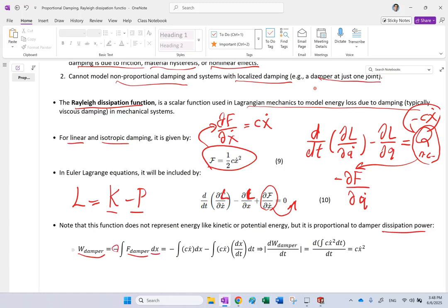That negative is because the damper is against the displacement, so there is a cosine of 180 degrees, the angle between them, because this is like F dot dr, and F of damper has this magnitude, dr has magnitude dx, and the angle between them is 180, so cosine of that is -1. Now F of damper is c x dot, linear isotropic damper, and then dx, you write it. Now here I divide this dx by dt, multiply by dt, so this term becomes another x dot, so it becomes c x dot squared dt.